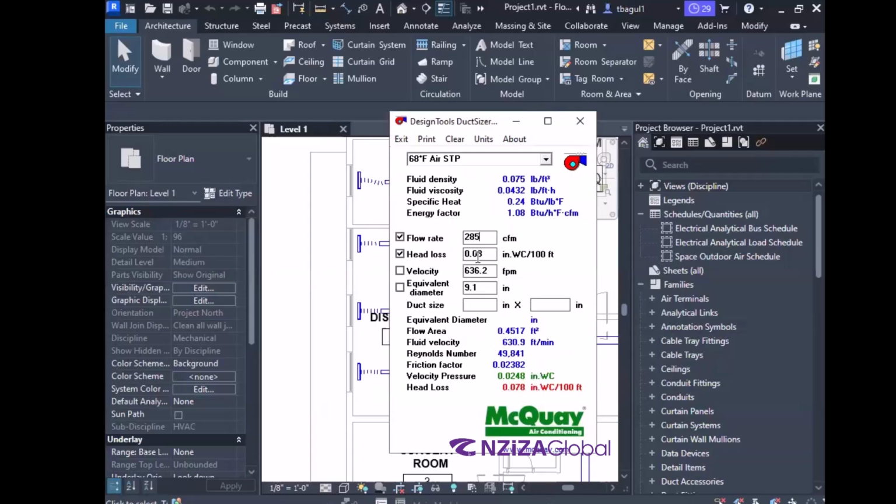But the ducts will not come in like 0.1 inches. It will usually come in 10 inch, 12 inch, 14 inch, so on and so forth, right? One more thing. Not every time you'll get the luxury of using a round duct. Most of the time you'll end up using a square duct to maximize the efficiency of the space, right? But right now, as you see, the equivalent diameter corresponds with a circle, right? So again, it is giving us a circular duct.